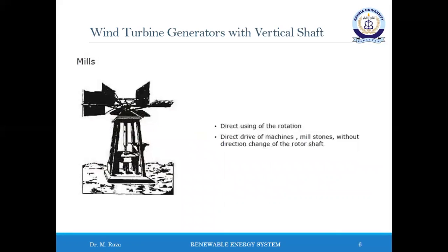The more recent horizontal axis wind turbines, such as the Dutch smock mill, designed for a higher tip speed ratio, require a far more sophisticated construction, not only for redirecting and back gearing the rotational movement from the horizontal to the vertical axis, but also for the much more complicated bearing of the faster and heavier horizontal shaft. The windmill, like the cup anemometer, belongs to drag-driven rotors with a relatively low tip speed ratio.